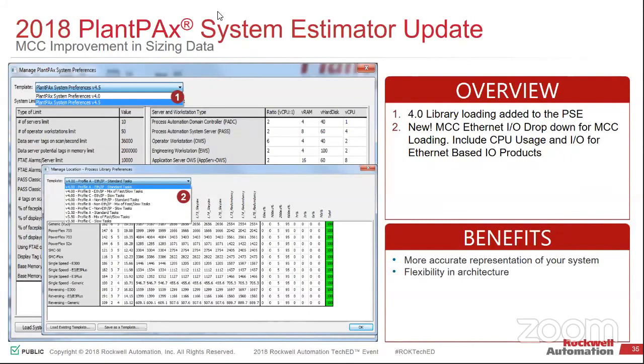It might not be a flat network. It might be dividing your power from your state control. You need to take a look at the network loading when you add an MCC to it and see if it adds to it. I think it's more taxing. Now, someone else might say differently, but I've seen more loading with an MCC. It can be addressed. It's not a big deal, provided you design the network around it.